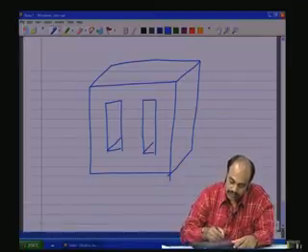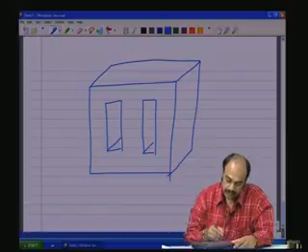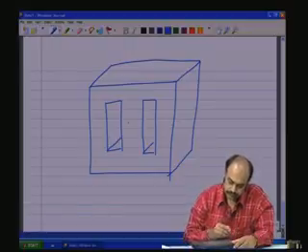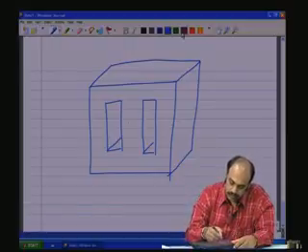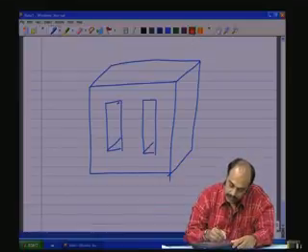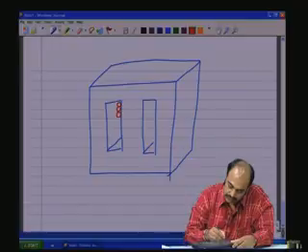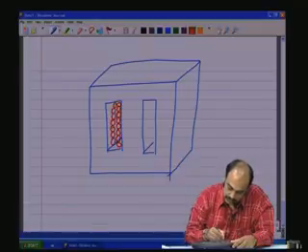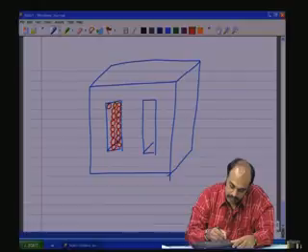So, we have the winding around the central leg. What is the maximum amount of windings that one can accommodate? So, if I cut, you will see that this is the number of windings that can be accommodated, both primary, secondary, all put together.